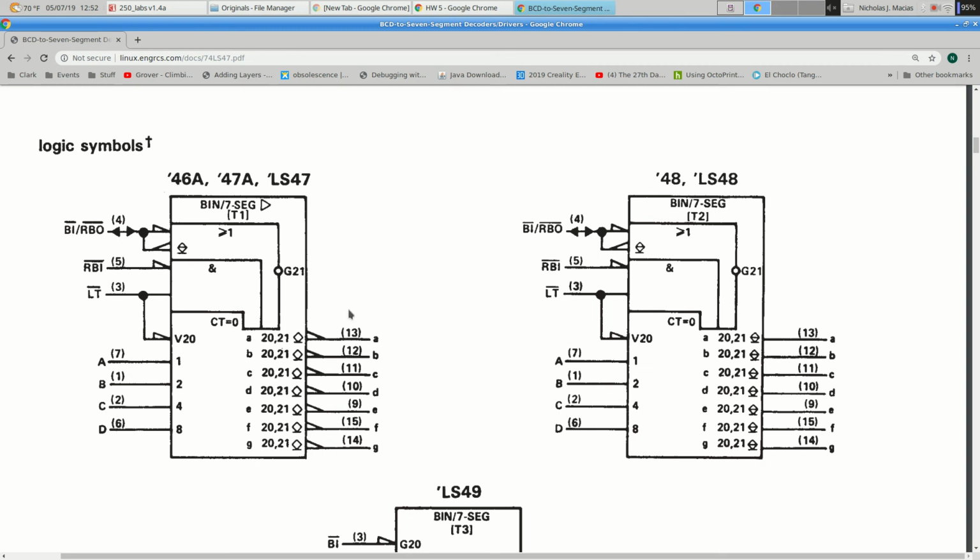And then hook up these to the 7 segments of your display. On your 7-segment display, connect 3 and 14 to power through a 1K resistor. Fire it up and you should get nice numbers being displayed.